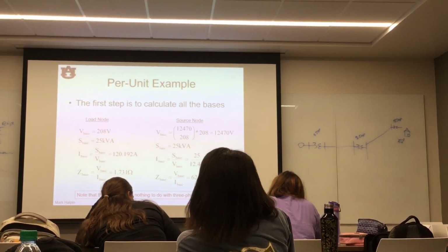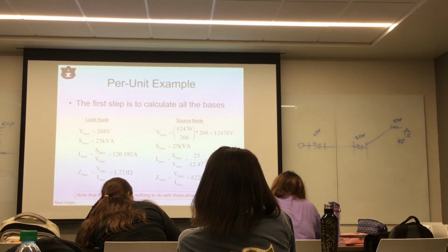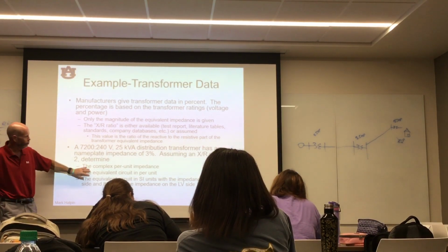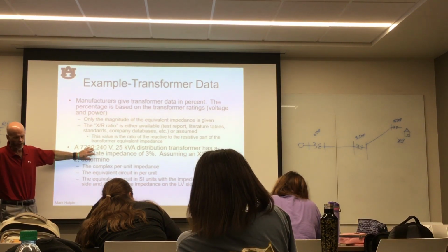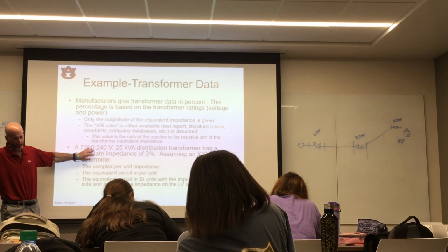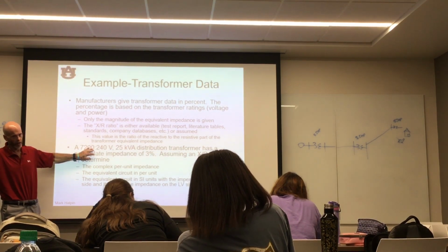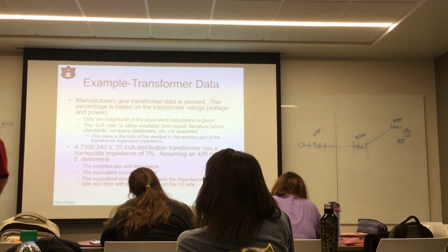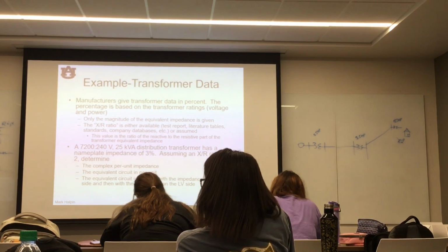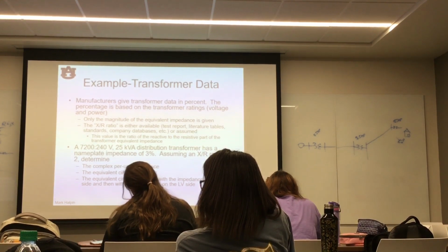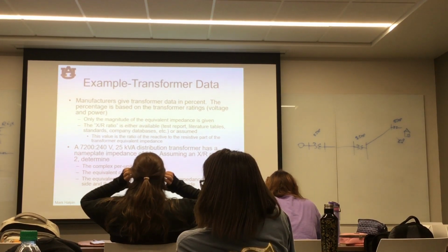Okay? And it's hard to see that when you look at a little problem like this one, because all we're doing is using the manufacturer's basis. Most of the time, our bases are going to be different from those of the manufacturer, particularly the power base. We will see when we get into bigger circuits, the power base, once we pick it, is the same for the whole problem. Voltage bases vary based on transformers.